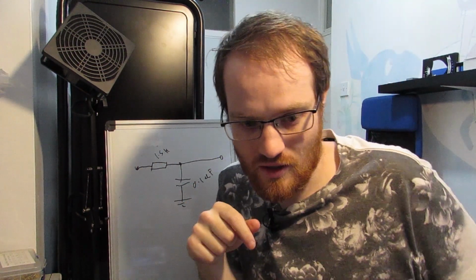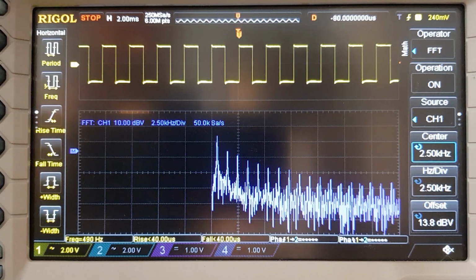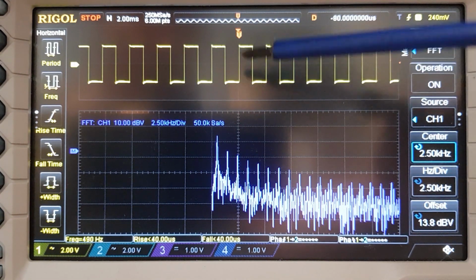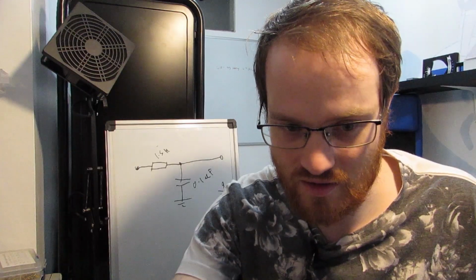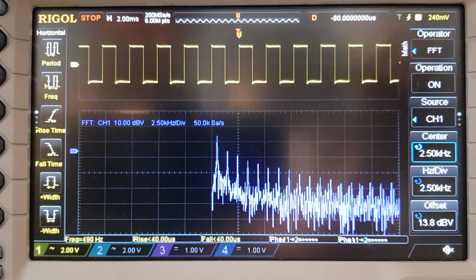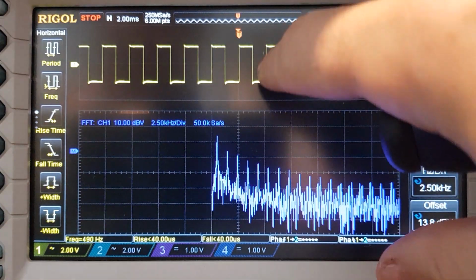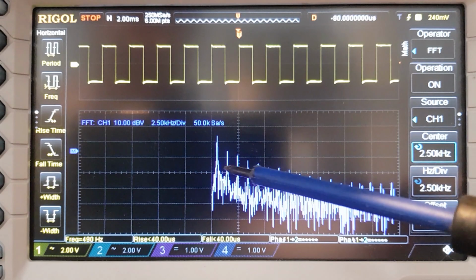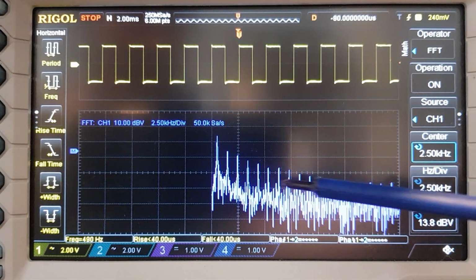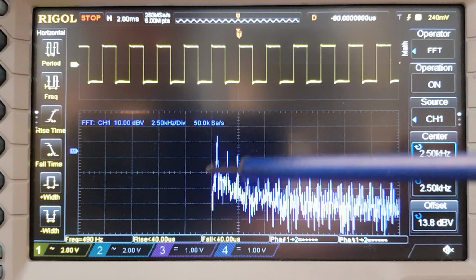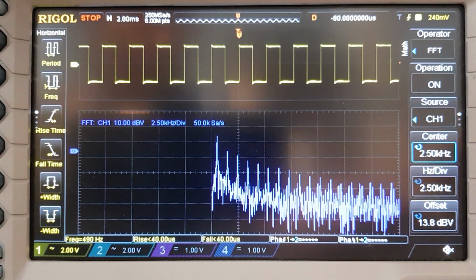And now I'll unfreeze the scope. So what we're looking for is we're going to see a big change in the shape. Generally when you see sharp edges like this, you think high frequency. So we should have softer edges. They'll kind of come up like this, like a kind of rounded off triangle. And we should see a lot of this high frequency information lower down, and we should see not too much attenuation of the fundamental frequency here.